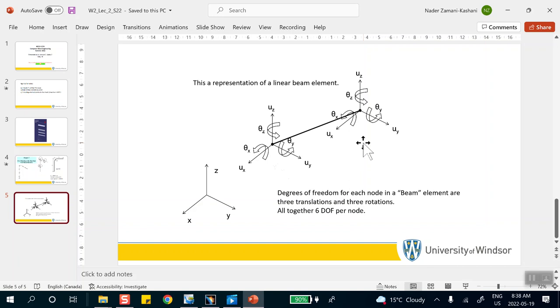In solids, if you took a plane, you cut them apart with a plane, and that plane was a plane of symmetry. For example, XZ, just hypothetically say XZ was a plane of symmetry. What do you know about the degrees of freedom for a solid element? XZ is a plane of symmetry. What do you know about translation of things on that plane?